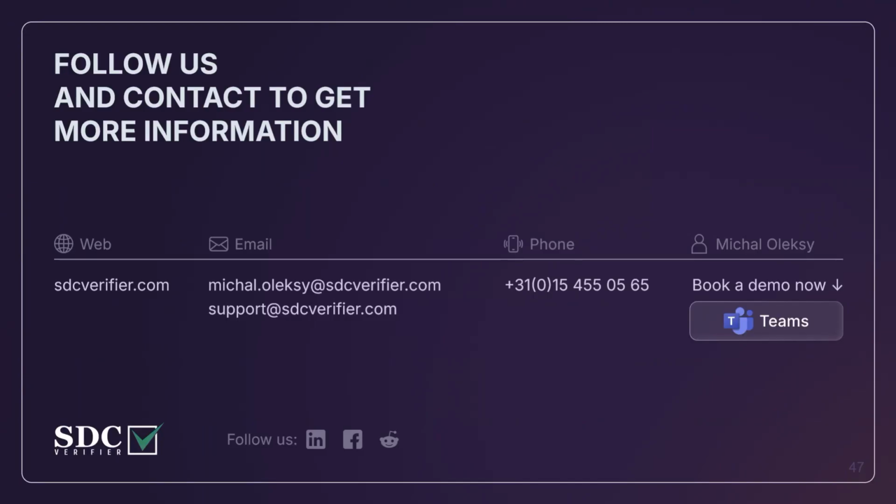Does SDC Verifier have the capability to import ANSYS LS-DYNA input and output files now, or is it being developed? SDC connects to LS-DYNA, so it will read the inputs directly from ANSYS. You don't need to import it to SDC. It will read it simply from ANSYS LS-DYNA, same as from a simple static structure in Mechanical, for example. So you can post-process them, and it's already available.